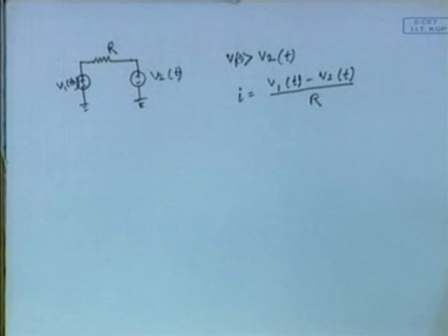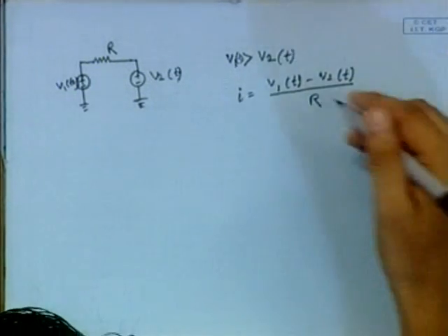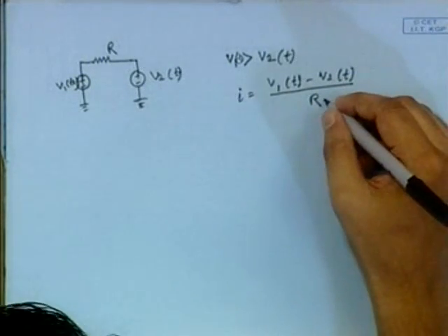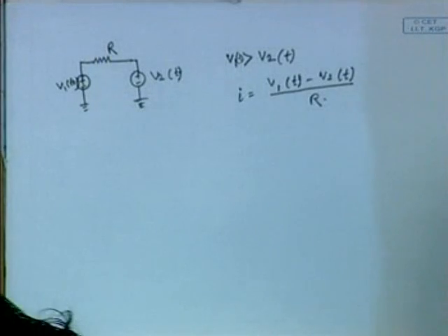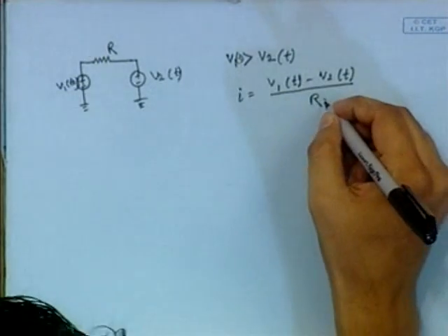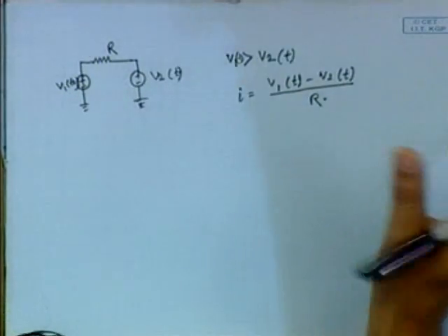At the same time, when we fabricate high resistance in the chip, the accuracy is also not very good. So there are problems implementing a high value resistor in the chip. That is why we have a new design to replace this R using the switch capacitor technique.